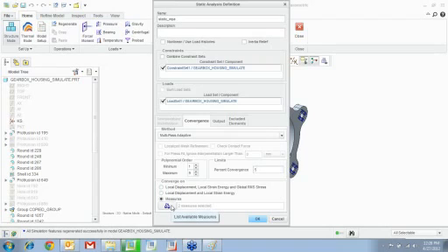Say for example, in the first pass the element edge order is 1 and our von Mises stress is 100. Now it runs another analysis at element edge order 2 in the second pass. It compares the difference between stress in the first pass and stress in the second pass and sees if it is within the 5% of convergence. If it's not, then it's going to bump up the polynomial order of the edge and go to a higher value. And then it will compare pass number 3 to pass number 2, so on and so forth.